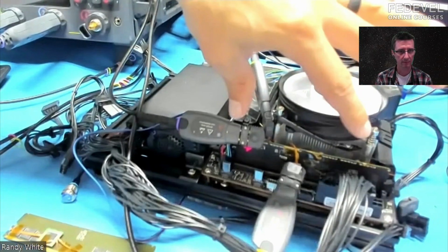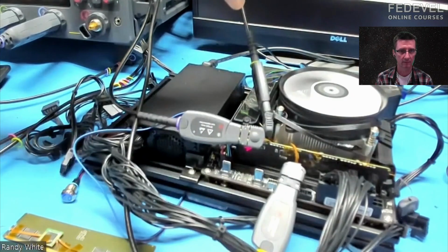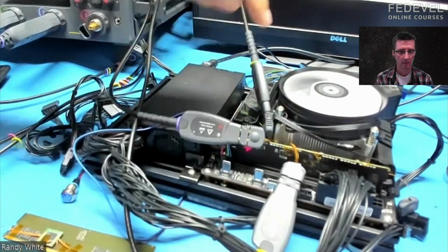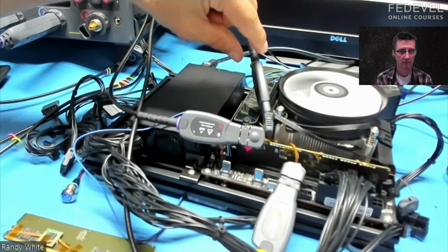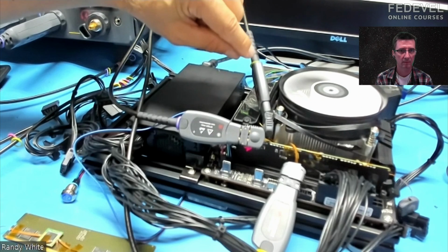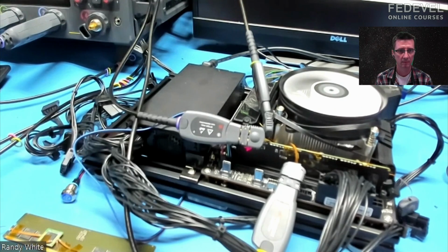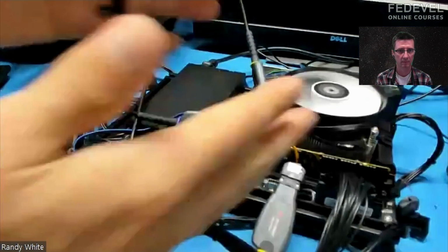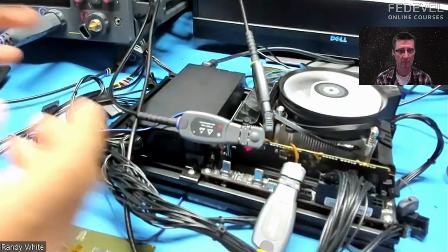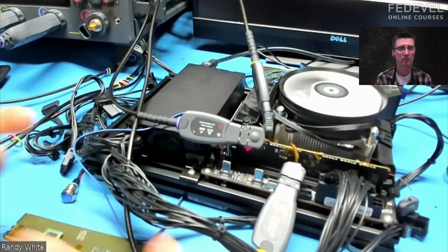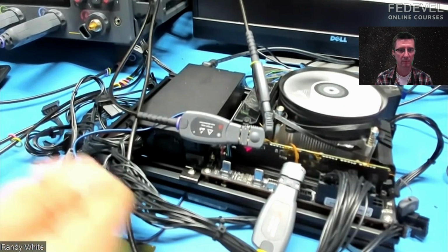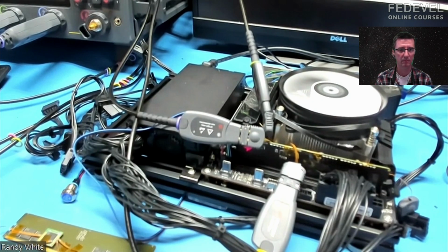Okay, I've got the probe attached. The system is running, and I've got 3 probes here. So here's 1, 2, and 3. I don't know if you could tell, but on the end of the probes, I have these color bands, these rubber bands, and those colors match the signal color on the scope. So whenever you're moving back and forth between the system and the scope, and you want to know which signal you're connected to, it's very common to have these color coded, just so you can track which signals you're measuring.